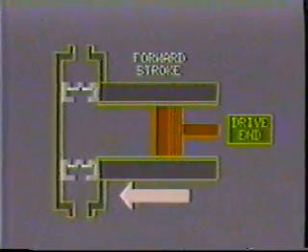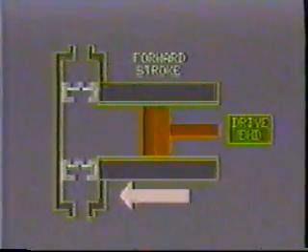That is, the thrust of the piston raises the pressure of the gas, and the gas is released, with the piston replacing the empty space. Movement of the piston from one end of the cylinder to the other end is the stroke. A forward stroke is movement of the piston away from the drive end of the compressor. Movement of the piston toward the drive end of the compressor is the backstroke.